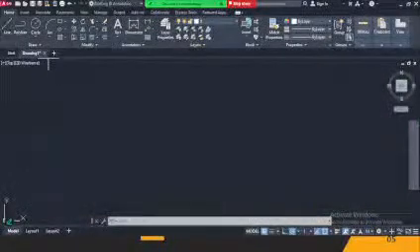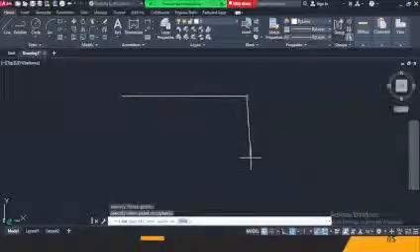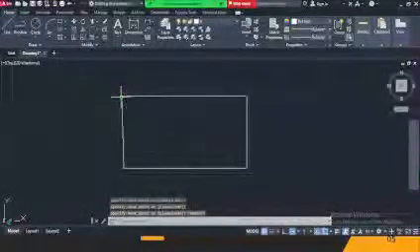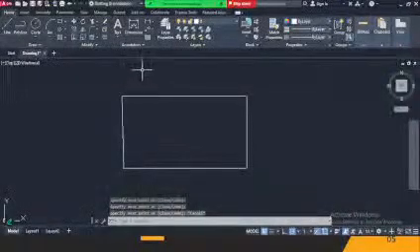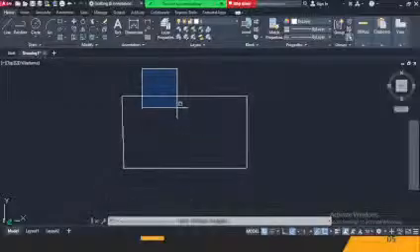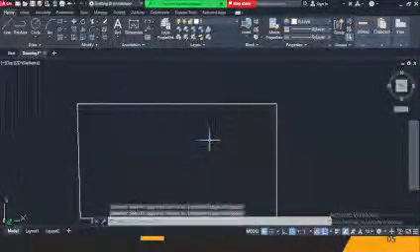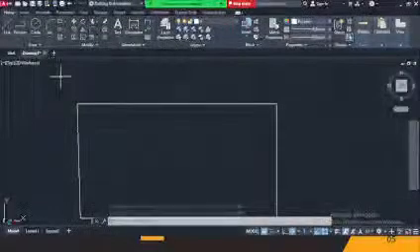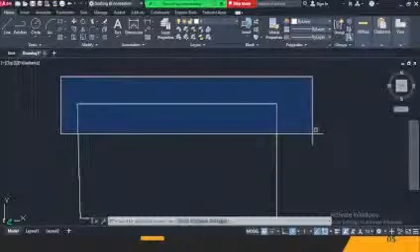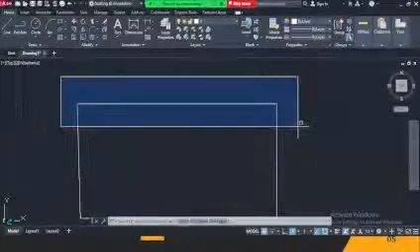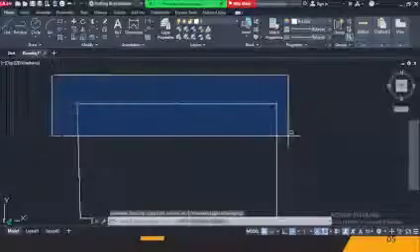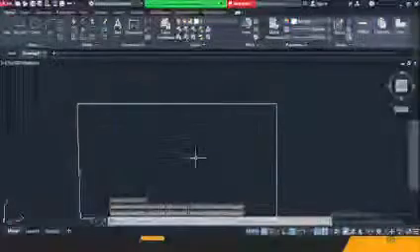I'm going to do a little illustration on that. For this, I'm going to draw a random object here, and hit my escape key. If I'm using the blue selection tool, you can see I have selected this line, but I can't select it. That is the way the blue marquee selection tool functions. You need to select the entire line. You can see I selected the entire line and it's selected, but if I select just a part, it can't.